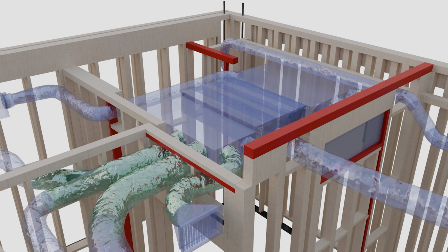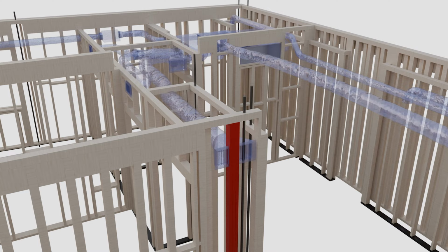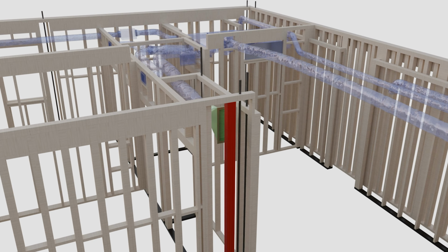At that point, you're stuck with 2 poor options. Either reroute critical systems, which can throw off ceiling heights, soffits, and fire ratings, or shift structural elements, which means redesigns, new calculations, and delays in inspections. All of it because structural and MEPF layouts were developed separately, without full coordination in the model. Fixing this in the field is not only hard and expensive, but can even lead to failed inspections.